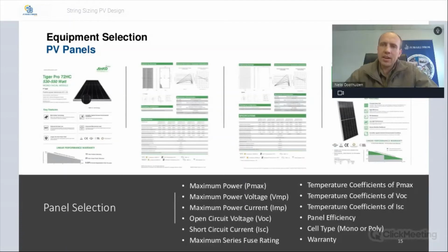So in their design, they could not use both inputs on the MPPT. They could only put one string per MPPT because the inverter could only handle 30 amps on the MPPT. With the 18.52, two strings attached to that one would be a lot greater than what the inverter could handle. So they would be running into clipping issues.